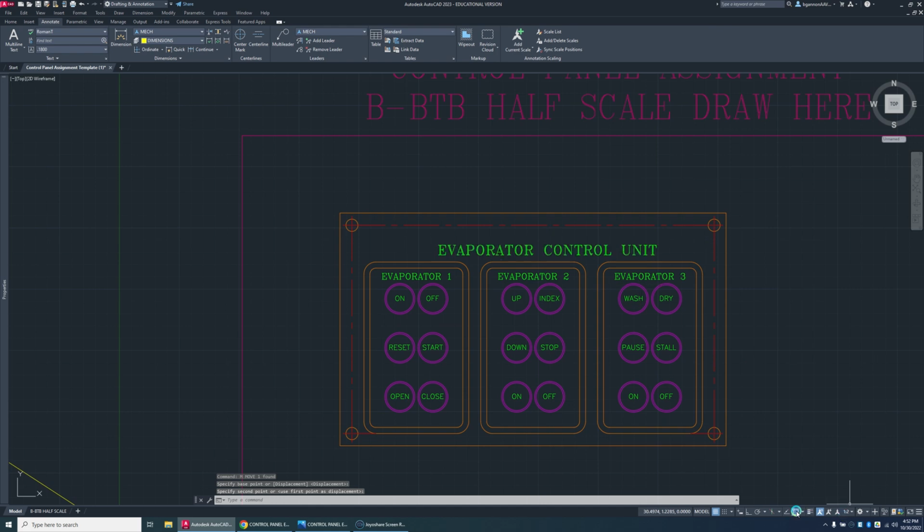So I'm going to turn off the object snap, and then come to center. Come to move, select my point, and I guess it can be better than that. So for offset, I'm going to offset it by 8.07 to find the center of this rectangle. Okay, that's not the right center. For offset, and then I'm going to 8.07. There we go. That looks much better. I got confused for a second there.